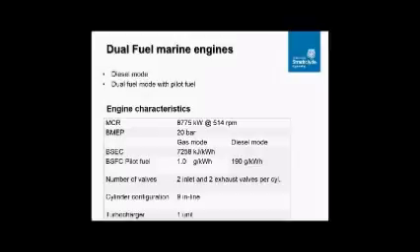The gas is mixed with air before the intake valves during the air intake period. After the compression phase, the gas-air mixture is ignited by a small amount of liquid pilot fuel. The air-gaseous fuel mixture does not auto-ignite due to its high auto-ignition temperature limit. The pilot fuel is injected near the end of the compression stroke to ignite the gaseous mixture.